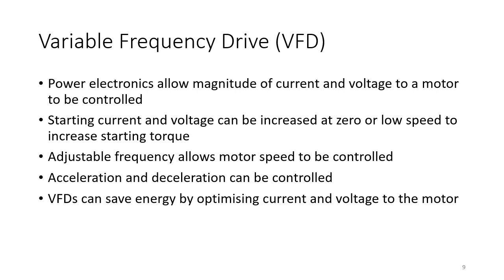The key point is that VFDs, as well as controlling the speed, can also save energy. So we optimize the current and the voltage to the motor, we optimize the frequency to the motor, and as a result of that we have control of the motor and we have the potential for energy savings. It also increases the life of the equipment, because we're reducing the mechanical shock, particularly by accelerating and decelerating more slowly than with direct online techniques. That can allow us to minimize the hardware shock when we start or stop the motor each time, and that can extend the life of the equipment as well.